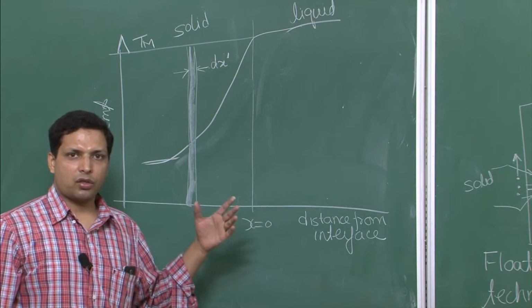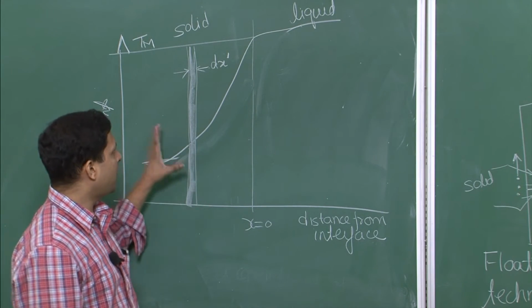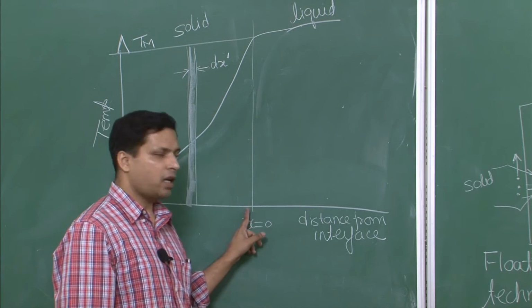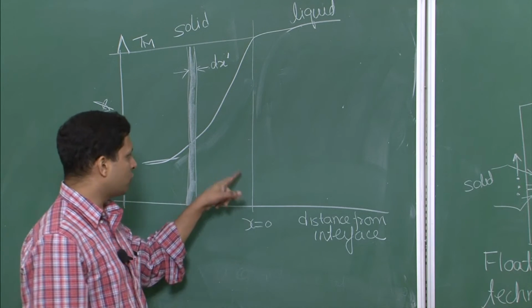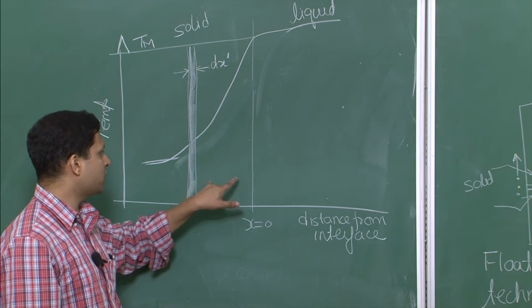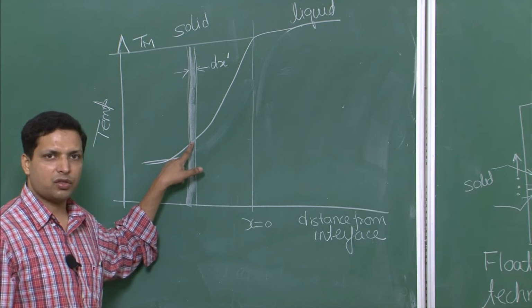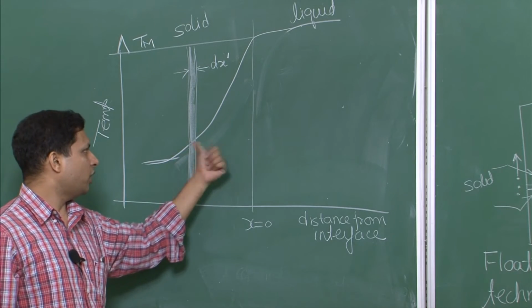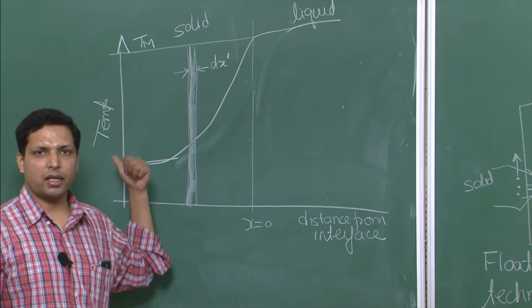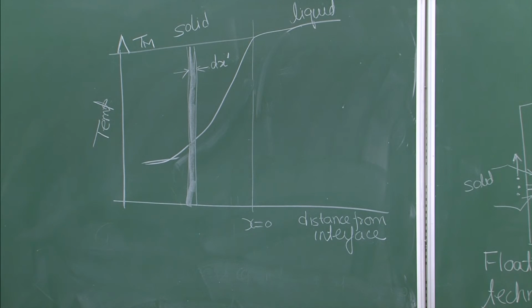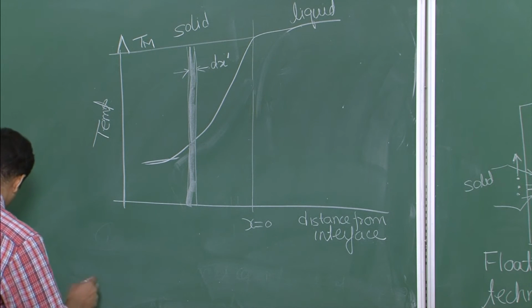When we are doing the solidification, this will be in a steady state, and therefore, the overall temperature profile near the interface would always look the same. At some distance x away the temperature would always be this value, and that means that whatever the heat flow is going into it, it is the same amount of heat that is going out from it, and therefore, we can write something like this, which says that